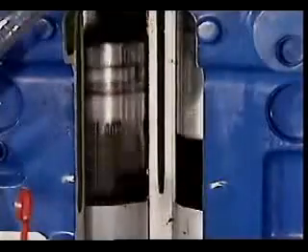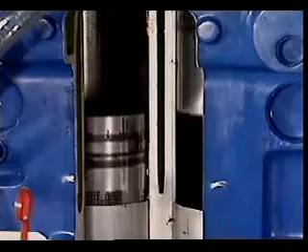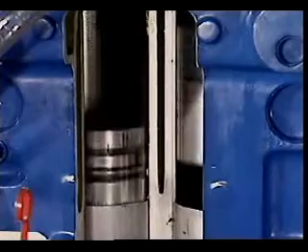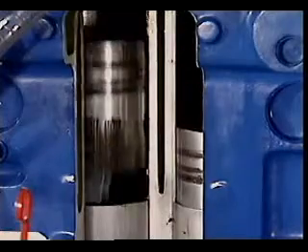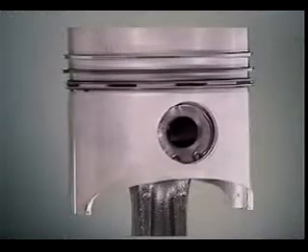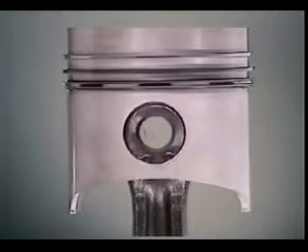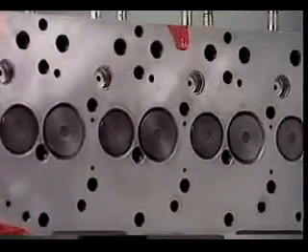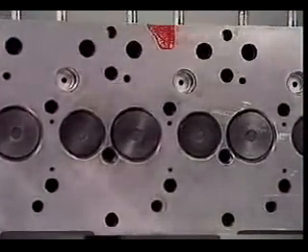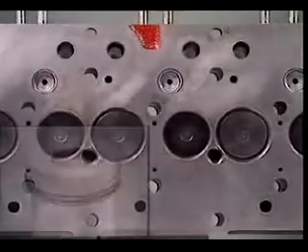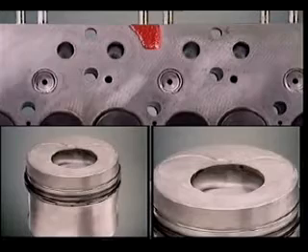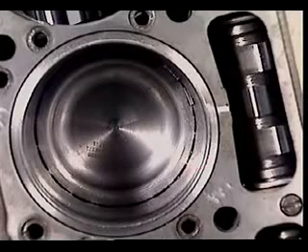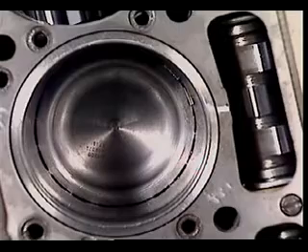Pistons in 2- and 4-stroke diesel engines can change directions hundreds of times a second and are exposed to extremes of heat and pressure. Modern pistons are made of aluminium alloys. Diesels using direct injection have an almost flat surface on the cylinder head, and almost all of the combustion chamber is in the head of the piston. Engines with indirect injection usually have pistons with a flatter head, and sometimes with small indentations.